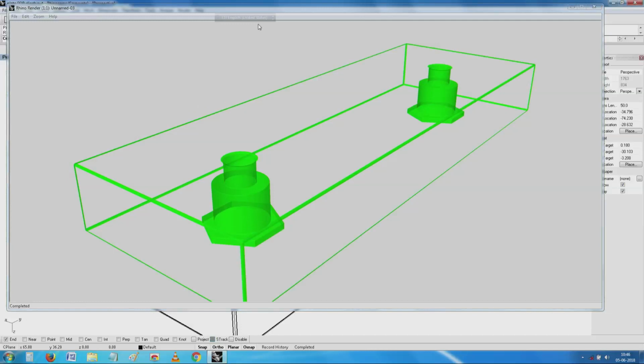Seen this, no? They are the edges of it, and inside we have that small depression which approximates to the nutsert, or the clinch nut, which I am going to push inside. And after putting the clinch nut, I will have a surface which is again, as said, 0.8 or 1 mm polycarbonate, which is generally hard, and depending on whether we have an adhesive which melts and sticks to that.